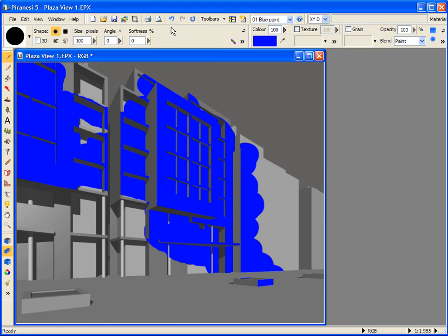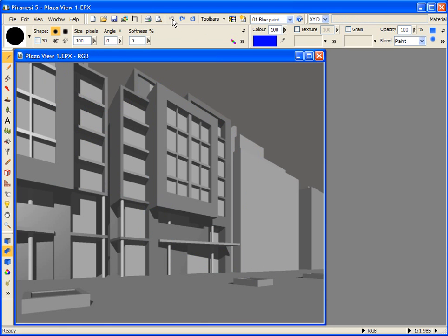I'll undo this so we can look at the material lock. This time I'll use the Clear Locks button to uncheck the orientation lock, and now click onto the material lock button. You can use a combination of plain, material, orientation and color locks to give greater control when painting. Okay, now I have the material lock checked, we can look at how paint is restricted to items in the scene by a material name.